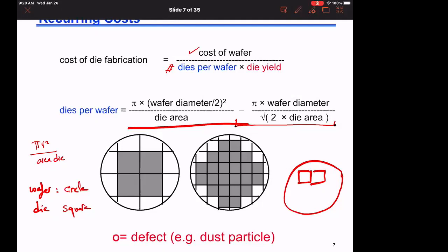It's very small, as we discussed last time, and a dust particle, just like the hair circumference that I showed you last time, can fall on the chip, and by mistake it can short two transistors together. If it shorts two transistors or two wires together, it is called a hard defect. Why is it called a hard defect? Because I cannot fix it, neither by increasing the voltage or lowering the temperature or anything. So the chip practically has to be thrown away because I cannot guarantee its functionality.